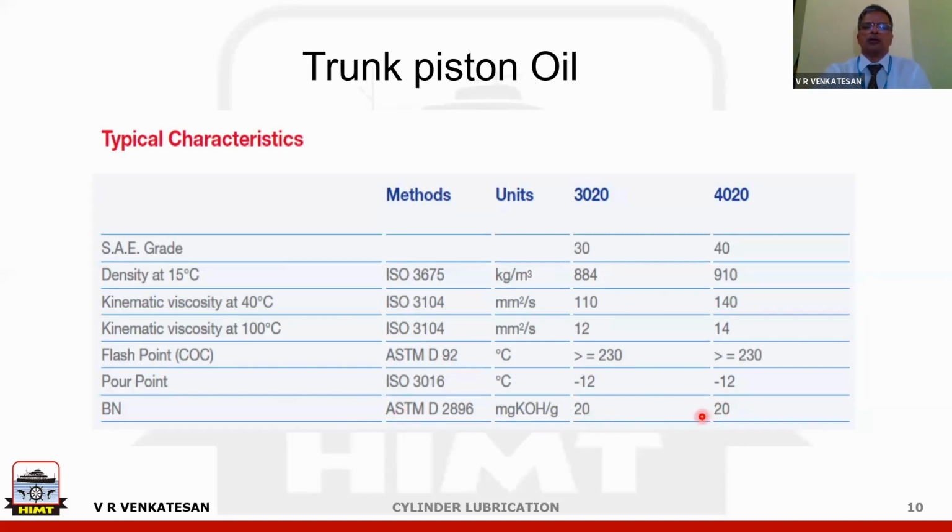Now this base number oil will be sufficient for burning low sulfur fuel. If it is a diesel engine, diesel fuel, this will be sufficient. If the trunk piston engine is running on high sulfur fuel, then the base number will be even more. Probably 40 will be required.